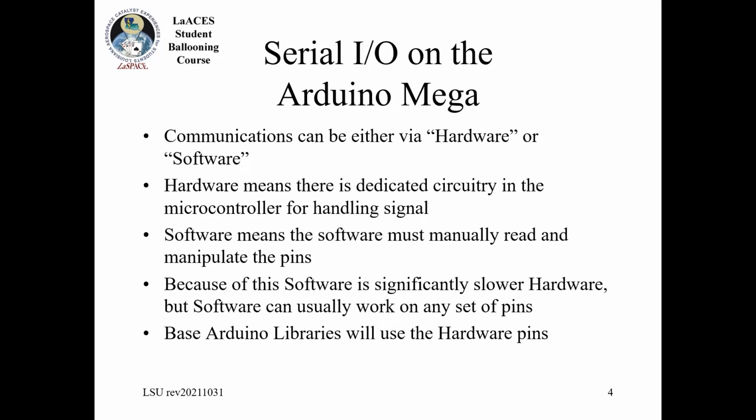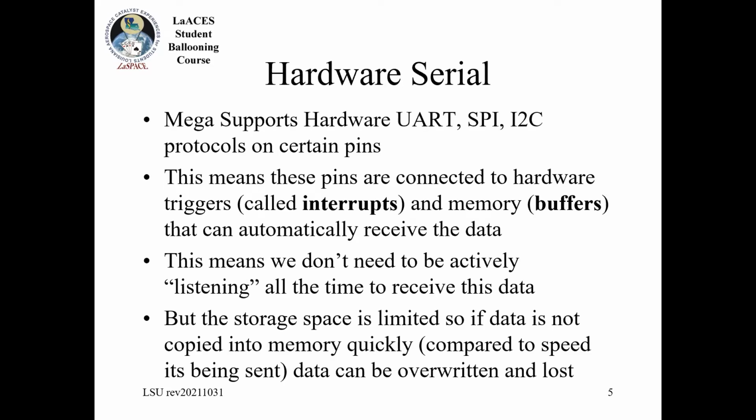But like I said, if possible, we want to use the hardware pins because they have actual design capabilities. It'll be faster. It'll be easier to actually get to work. So we've said this before, but we're going to keep saying it, right? You have specific pins that support your UART, which is your serial.